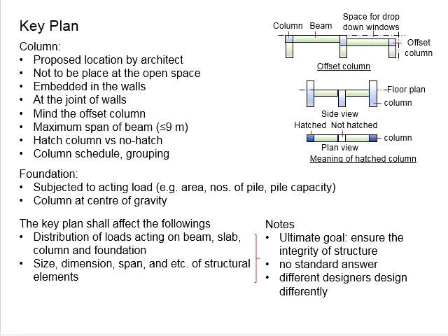There is a wide range of piles with different capacities, and there are several types of piles. There are RC piles, there are bakau piles, which are timber, and there are spun piles, where the piles are pre-stressed and able to carry a higher capacity of axial load. This will be very much dependent on the loads acting on the foundations, and you will need to decide the suitable piles to be used.